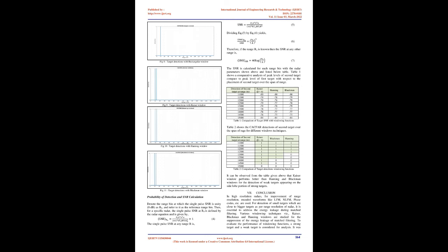The Blackman window is similar to Hanning window. The resulting spectrum has a wide peak, but good side lobe compression. There are two main types of this window. The 4-term Blackman is a good general-purpose window, having side lobe rejection in the high 90s dB and a moderately wide main lobe. The 7-term Blackman window function has all the dynamic range you should ever need, but it comes with a wide main lobe.